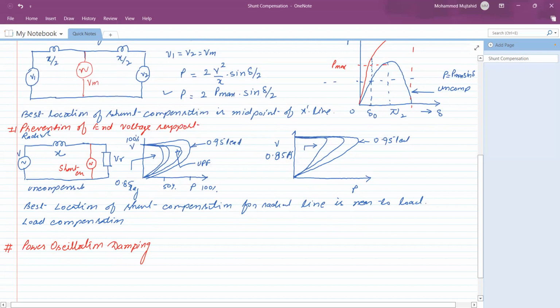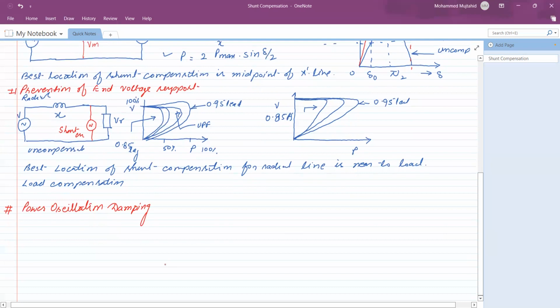Whenever there is a sudden increase in load, or there may be some perturbation, that angle takes some oscillation, and after some oscillation, it is going to reach the new equilibrium position. But this oscillation becomes very important if the system is very large and highly connected. We want the oscillation to die out very early. It means within 1.5 cycle, 2 cycle, it should die out. Otherwise, this oscillation may increase and take the system out of synchronism, isn't it?